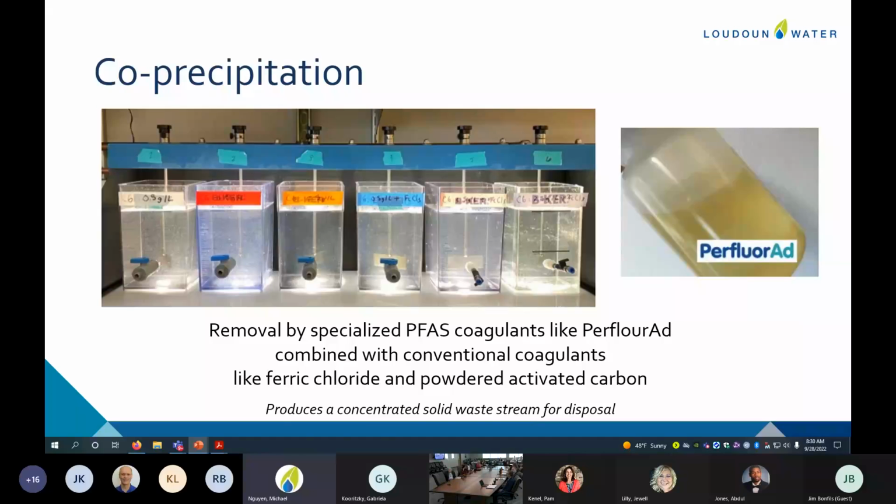If we can add that coagulant ahead of our GAC and encourage it to fall out of the liquid stream, it may help our final effluent. So we absolutely need to evaluate for the leachate what types of coagulation are going to help prepare and reduce contaminants. Most likely, this will end up being our pre-treatment step before the PFAS removal technologies that we're going to talk about.